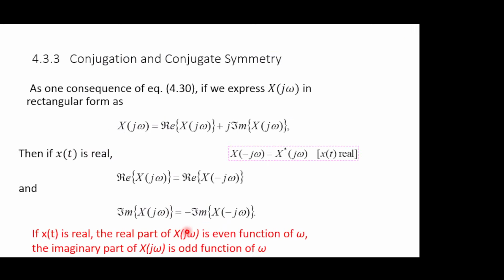Now we can think about things a little more, because now we think of big X of j omega as a function, so we analyze it a little more than our a_k. Now we analyze a whole bunch of things for real functions, the Fourier transform of a real function. First, we split this big X into real part and imaginary part.